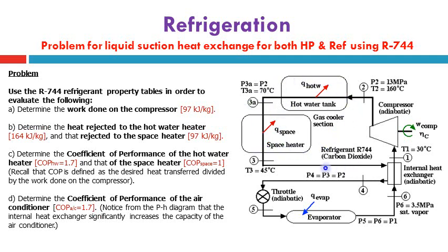Then after point 3, we will go to this internal heat exchanger with the suction line of the compressor to reduce the temperature of point 3 from 45 by a certain degree, by gas cooling, not subcooling, since there is no condensation process, as will be shown on the next slide when presenting this line diagram on the pH diagram dedicated for CO2.